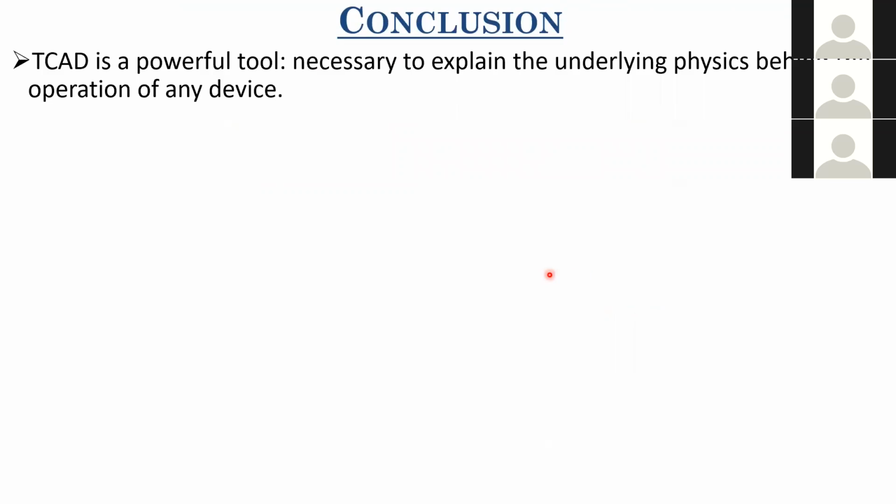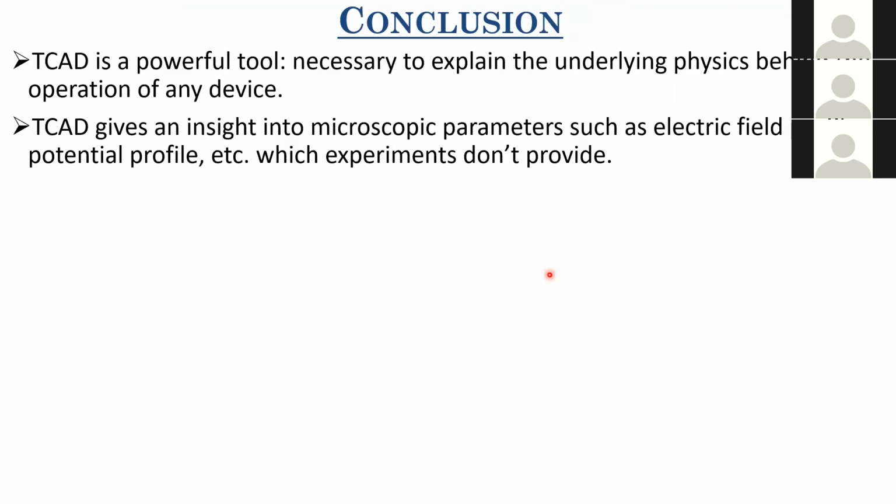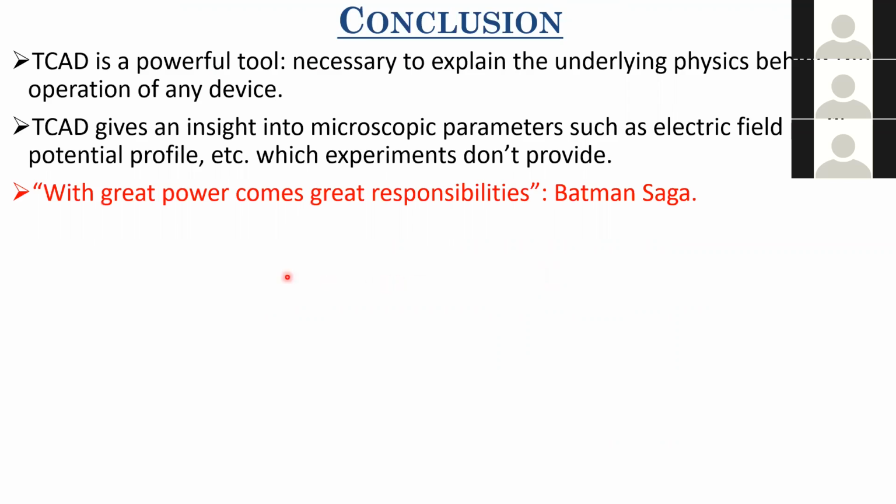So TCAD is a very powerful tool. It's necessary to explain the underlying physics behind the operation of any device. It gives you an insight into the microscopic parameters such as electric field, potential profile, carrier density, doping profiles, which your experiments can't provide. However, as it is said, with great power comes great responsibilities. So as a user, it's your responsibility to use this judiciously.